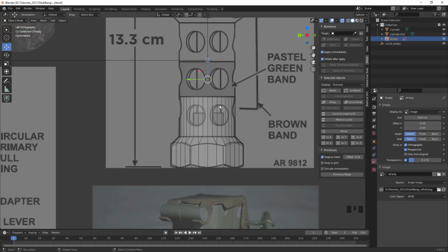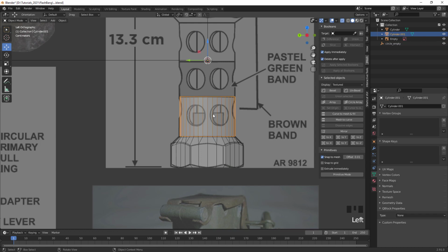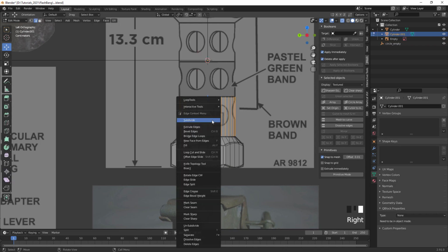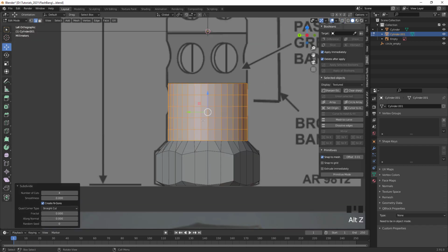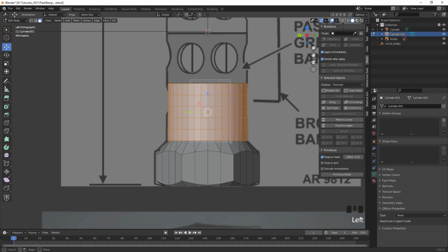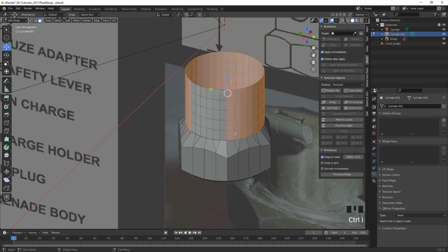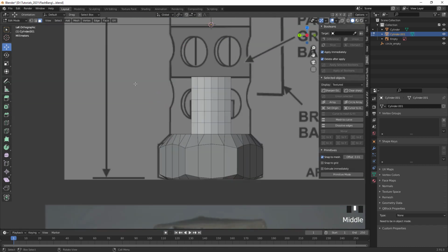So next, let's go back to that object that we separated out. I'm gonna press Ctrl and A to make a ring selection, and then I subdivide it 4 times. So that we have more edges here that we can work with. So now let's draw a selection so that we have these faces selected. I reverse the selection and delete the faces.